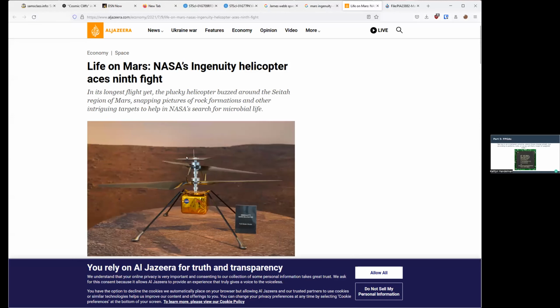We can see the antenna on top, and we can actually use the size of that antenna to deduce what frequency it's broadcasting at. And I think I calculated around 900 megahertz, meaning that it's actually not broadcasting directly to the satellites. And we can also tell it's not broadcasting directly to the satellites because it's vertically polarized.